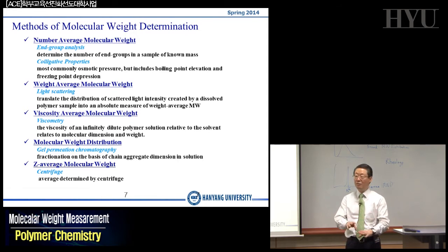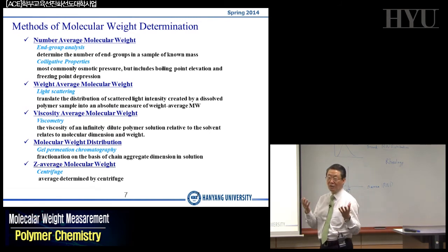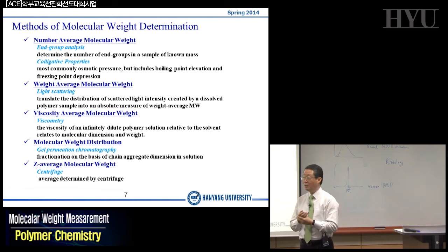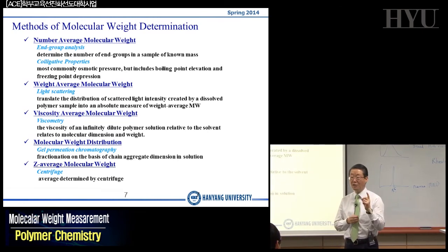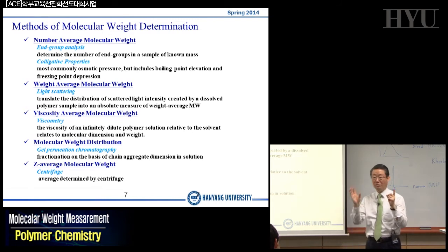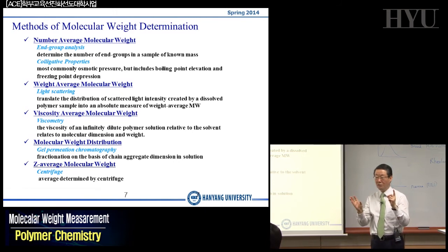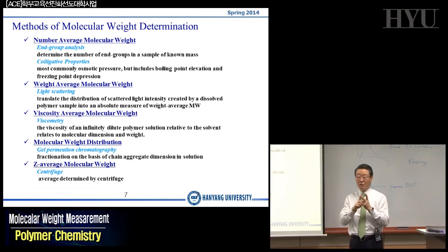Okay, we have already defined the molecular weights. As we have already seen the glass transition temperature in our chapter 4, if you remember how we can calculate the crystallinity, perhaps you can remember 2 ways of measuring the crystallinity, right? The first is DSC, right? DSC, the melting behavior of the crystals, and the second way is diffraction, right? Wide-angle diffraction methods, so that if there is any peak, then you can integrate those peaks and calculate the crystallinity.